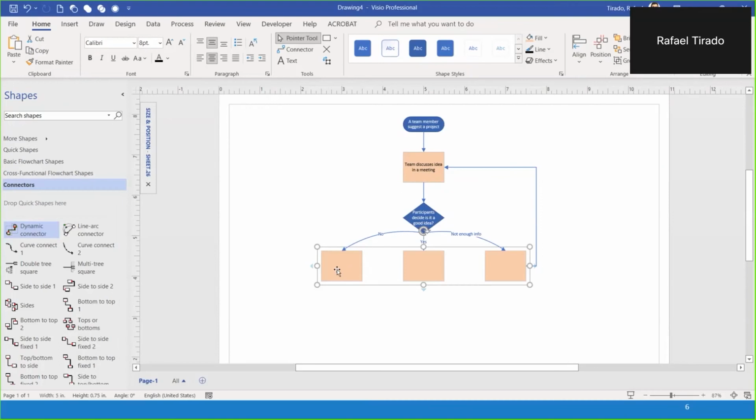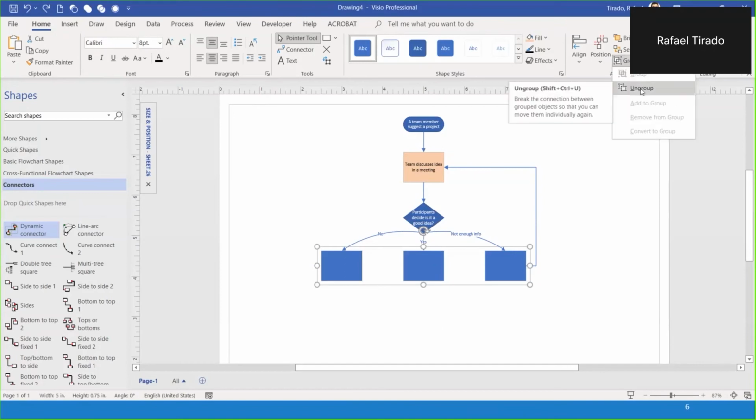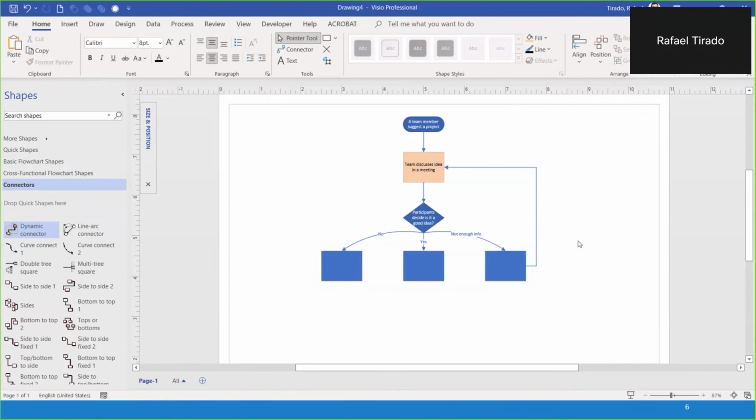So what I should rather do over here, if I want the formatting to apply only to that particular shape, then let me just undo over here. Before I copy the formatting, I'm going to ungroup these shapes. I don't need to have them grouped because I already used them to position them where I wanted to. So I'm gonna go over here to the same group option, and now I'm going to ungroup them. All right, so now that they are ungrouped, I can take this shape, copy the format, go over there, and then paste it, and it will affect only one shape.